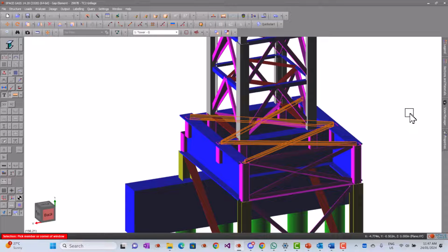The primary function of the bracing is to counter lateral loads, while the girders are meant to withstand vertical bending loads. With the introduction of gap elements, you can now assign gaps to the ends of members. This feature is especially beneficial for bracing members, as the bolt hole tolerance often significantly reduces bracing loads, effectively redirecting bending moments back into the main girders, where they are designed to be absorbed.